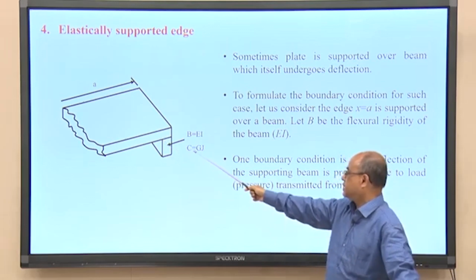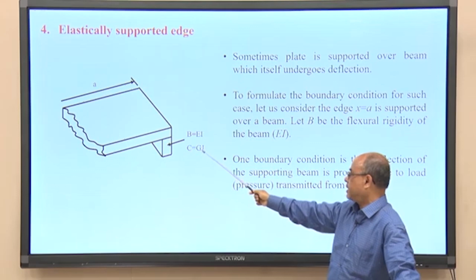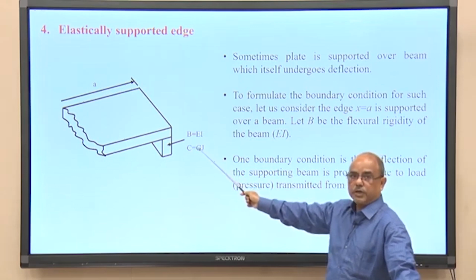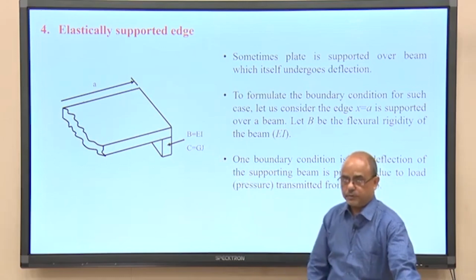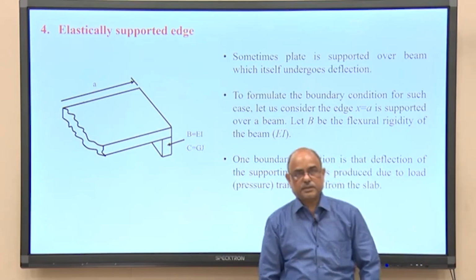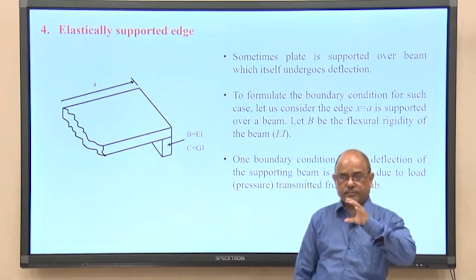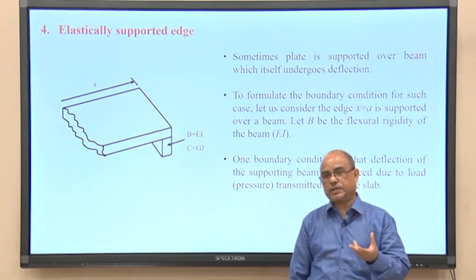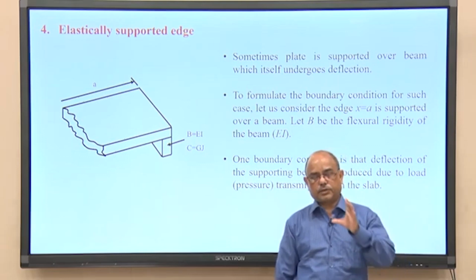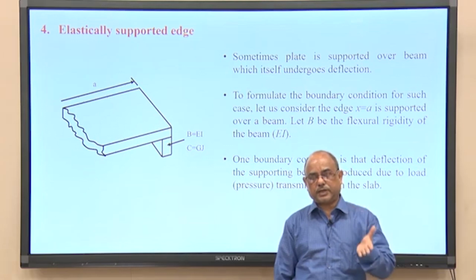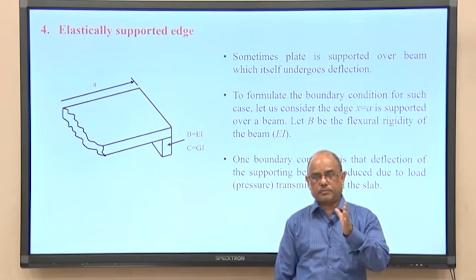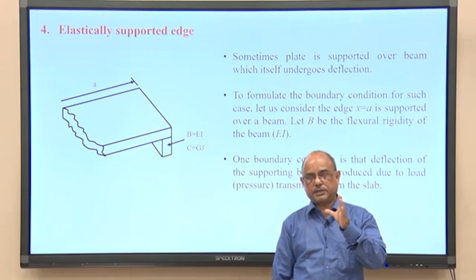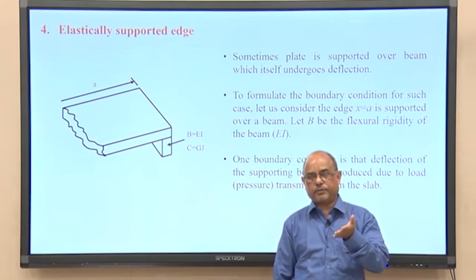Then the torsional rigidity of the beam. Torsional rigidity is defined as the product of shear modulus and torsional constant J. The torsional constant J is slightly difficult to find, especially for a rectangular section, because a rigorous solution is obtained for the torsional constant, and a chart was given in the book Theory of Elasticity by Timoshenko for rectangular beams of different width-depth ratios. So, coefficients are given and you can find it from those coefficients.